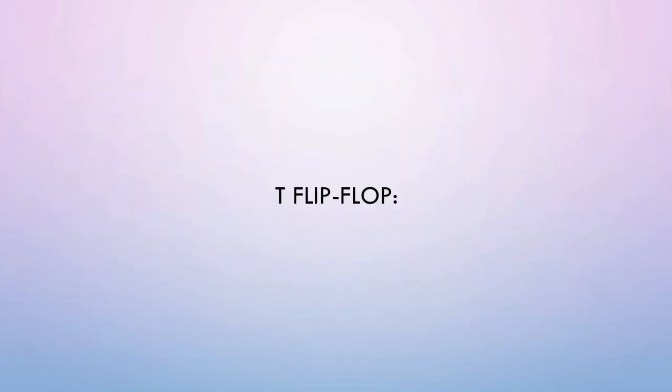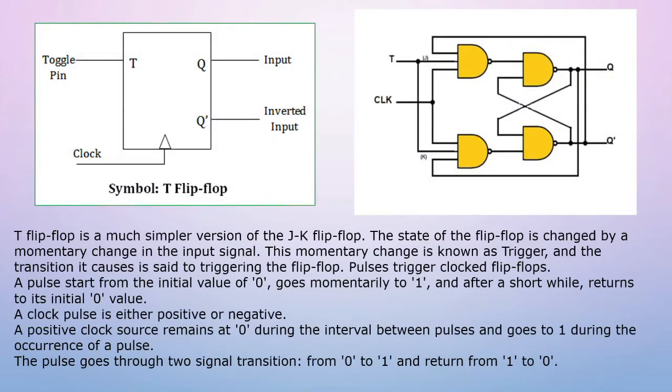Next, T flip-flop. T flip-flop is a much simpler version of JK flip-flop. The state of the flip-flop is changed by the momentary change in this input signal. Momentary change is known as a trigger, and the transition is said to be triggering the flip-flop. The pulse triggers clock flip-flops.